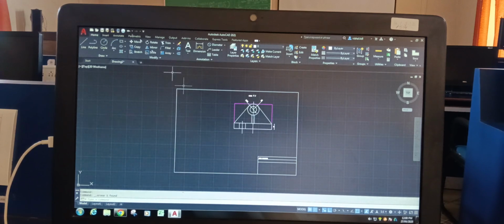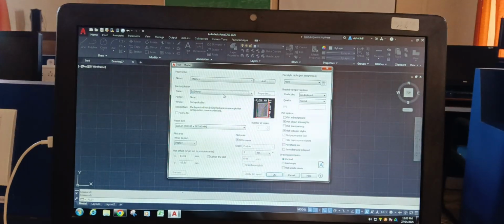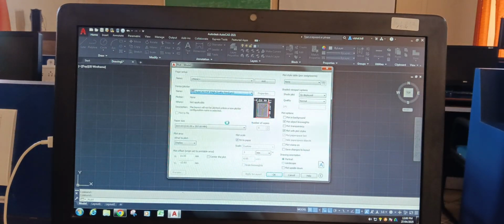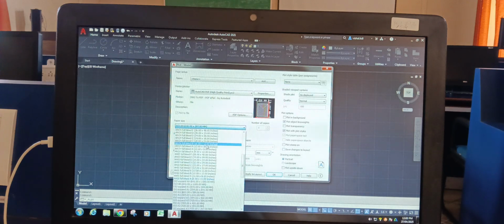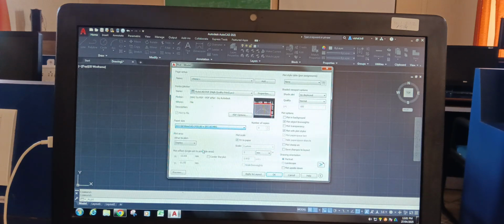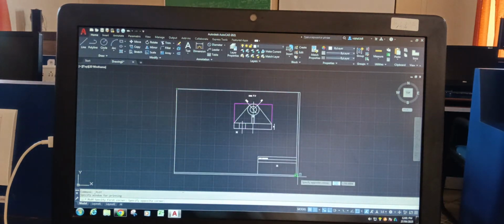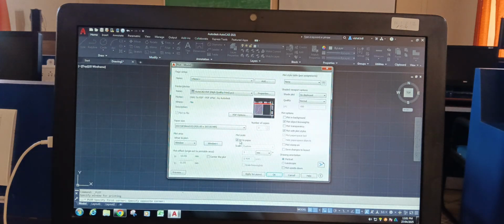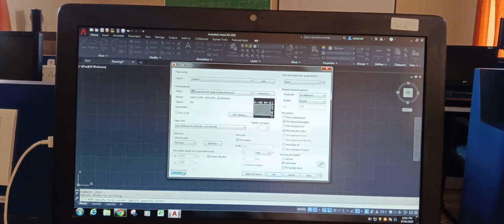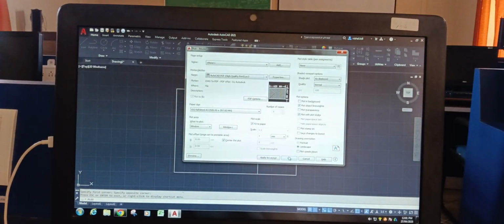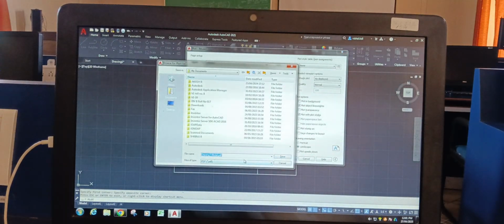And then you can use the print option. Go to the print settings, select the printer as AutoCAD PDF, and change the paper size to Full Bleed ISO A3, which is 420 by 297. For what to plot, instead of Display select Window. Now select this. Then use Fit to Paper, Center the plot and use the landscape setting. In this way we can preview that. So this is your final print. Then if I click on Plot or OK, you can directly save that in PDF format.